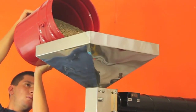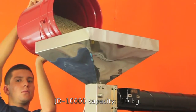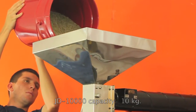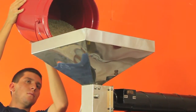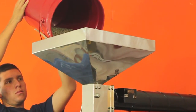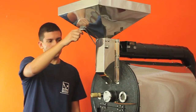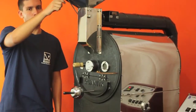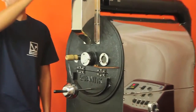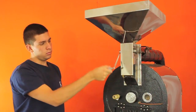Roasting the coffee. Deposit the coffee inside the hopper, no more weight than the previously established for each machine. Pull the loading door, allowing the entrance of the coffee into the cylinder. Wait until all the coffee passes through. Close the loading door.